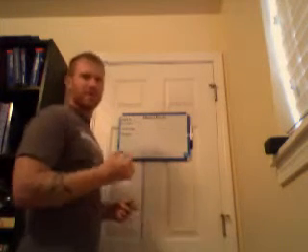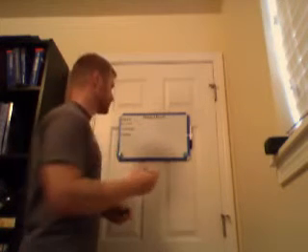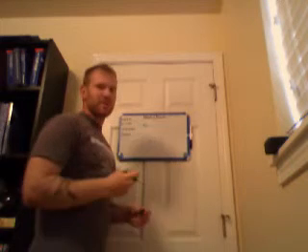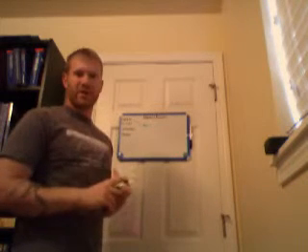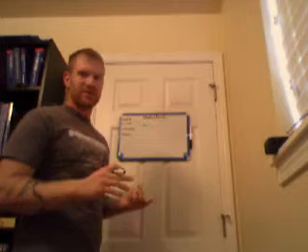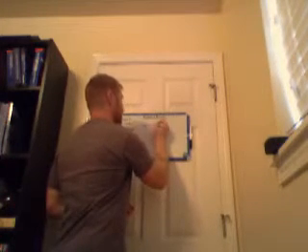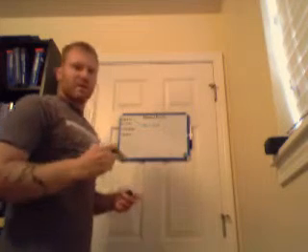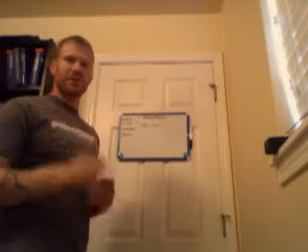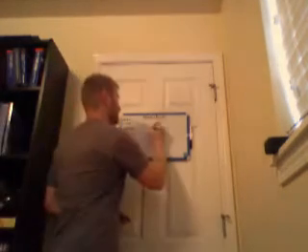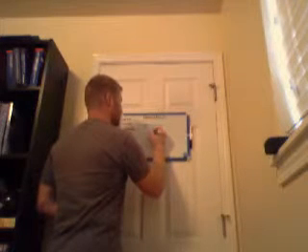The first weight I want to talk about is basic empty weight. Basic empty weight is the weight of the aircraft with all equipment installed. So you've got the aircraft at no fuel, but also full operating fluids. So your engine oil, transmission fluid, hydraulic fluid, all that kind of stuff. So you've got zero fuel and full fluids.